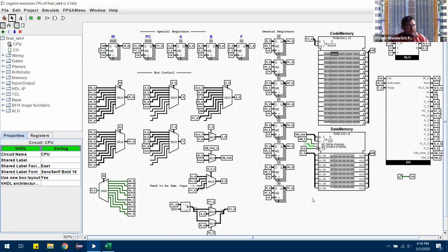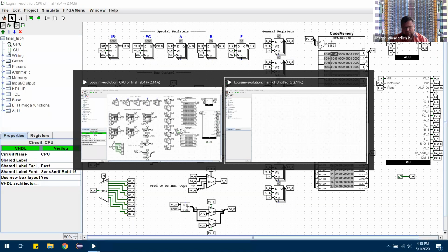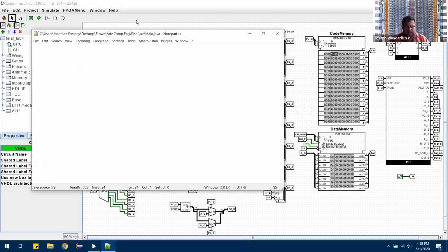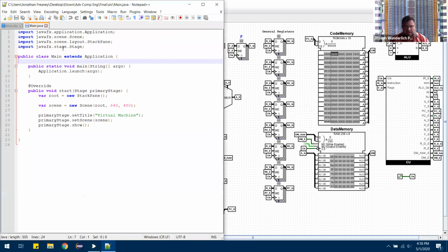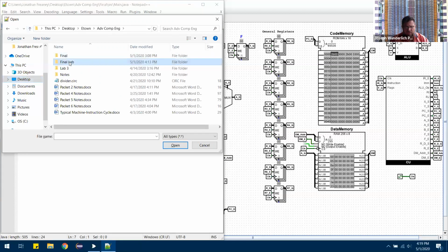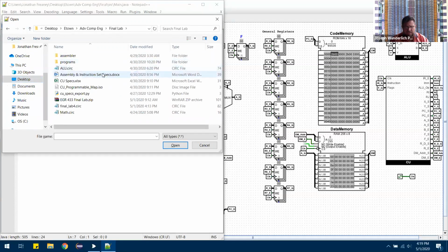It's a little tricky. If you remember in 333 class, the input and output ports of the 251 microcontroller, there's different weird things you got to do there. You need input and output buffers, and then you need pull up resistors and things to actually get the signals to work coming out. So to deal with the actual outside world, not that you would need that in a logic simulation, is a whole other level. This is just one of a series of labs, a couple labs.